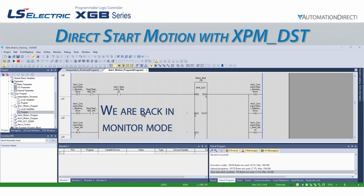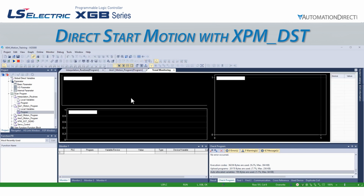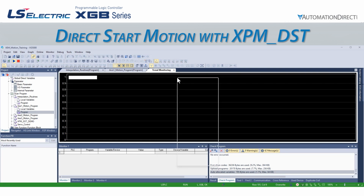Let's trigger our move and watch it execute in the Trend Monitoring tab. First, let's go out of monitoring mode so we can avoid filling our trend with empty data. We will then go to Monitor, Trend Monitoring, unselect View Bit Graph and Display XY Graph, and add Axis 1 CurPos to our trend graph.